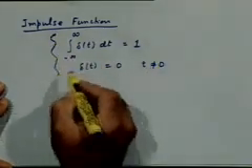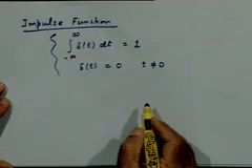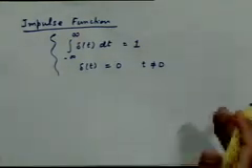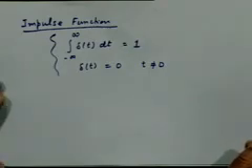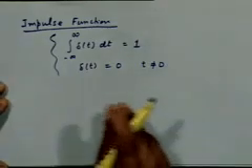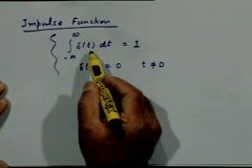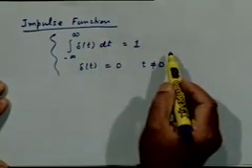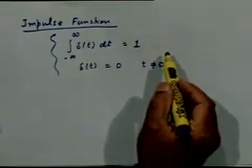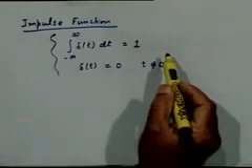Right? This is one definition of a number of possible definitions of an impulse function. Some people sometimes write by mistake delta of t equal to 1 at t equal to 0. Now that is wrong, right? Delta of t at t equal to 0 is undefined, it is actually infinity.